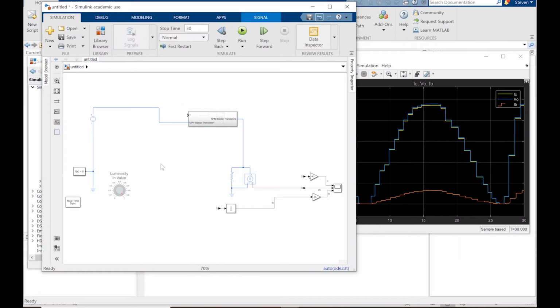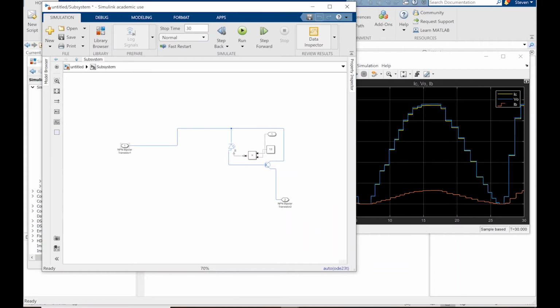Here I am deleting that, and I want my model to look physically like an NPN phototransistor. Here I'm just going through. There's too long of a title. I'm going to type emitter and collector, or collector then emitter, and later on when I'm editing the library, I'm going to change that to E and C, because everybody who works with the transistor is probably familiar with the difference between the emitter and collector.